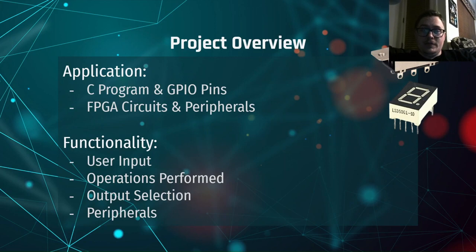And then if we were to flip switch 1 instead of switch 0, we would actually be selecting the output of the multiplexer. That quad 2-to-1 multiplexer is a circuit in the project that will pass one of the 4-bit inputs to the output. And if we flip it, it will go from the arithmetic unit being displayed to the Boolean logic unit being displayed. And that's where that output selection happens.